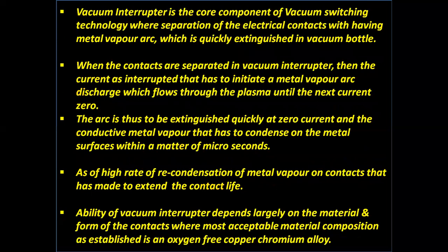The vacuum interrupter is the core component of vacuum switching technology, where the electrical contacts separate with a metal vapor arc, which is quickly extinguished in the vacuum bottle.